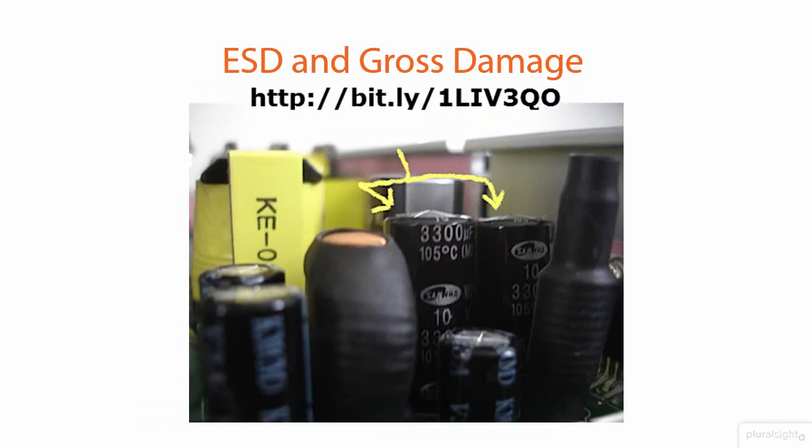The other thing is the distended capacitor. Distension refers to puffing out. So as you see, these capacitors are likely to explode. It looks like some sort of problem has happened inside the units to make them bulge out. That's not a good situation to see. And like I said, I've never attempted and would never attempt to replace an individual capacitor on a motherboard. I know people who are good enough with electronics to do that, but I personally wouldn't recommend it. I would suggest you try for a warranty motherboard replacement because this is definitely a manufacturer's error in most cases.